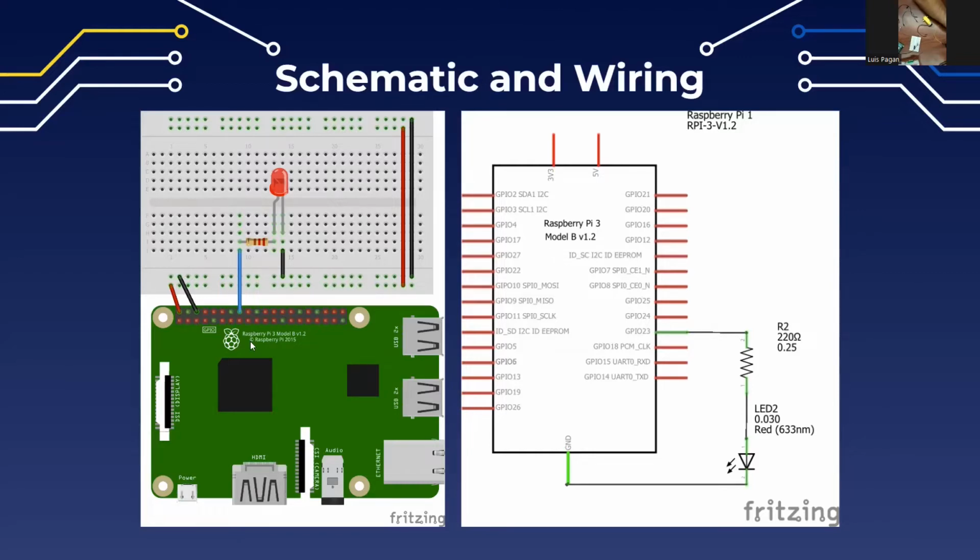So if we take a look at the actual connections that I'm making, you can see here, this pin at the top, these two pins are VCC, so they output 5 volts. So what I'm doing is I'm connecting them to that 5 volt lane on the breadboard, and here the same thing with ground, which is located 2 ports down from the top, or 3 ports, sorry, and that's connected to the negative terminal.